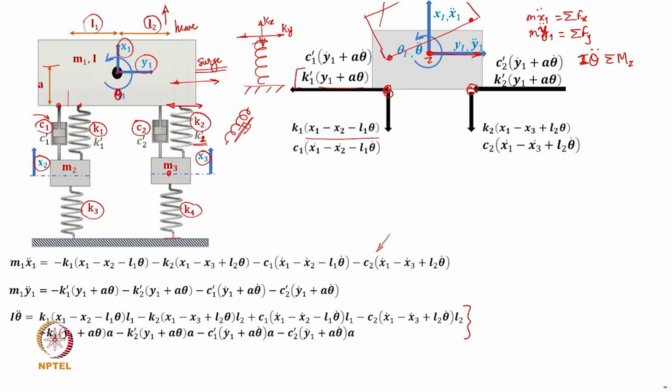Now, having obtained these forces acting on the free body, now you can actually generate the governing equation by applying Newton's law. So, if you look at all the vertical forces or a vertical motion, mass times acceleration will be summation of all the forces in the direction of acceleration in the vertical direction. If you use this, you will get this expression, which basically is going to be the governing equation of motion for the degree of freedom x1. On similar lines, you can also look at the motion of this free body or a chassis in the y direction. So, y1 double dash will be summation of all horizontal forces acting on the mass. So, if you do that, this is what the equation you get,